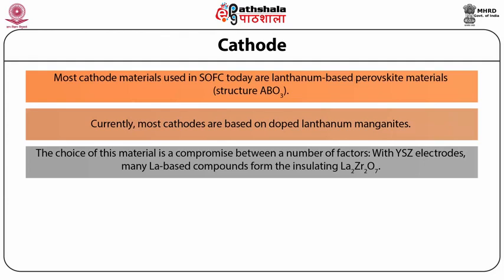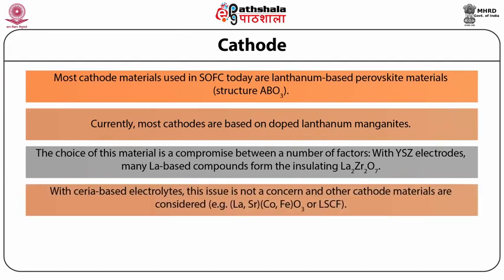With YSZ electrolyte, many lanthanum-based components form the insulating lanthanum zirconate. With ceria-based electrolyte, this issue is not a concern and other cathode materials are considered. For low temperature cells, the conductivity of LSM, that is lanthanum manganite, is inadequate and other materials such as strontium doped lanthanum ferrite, that is LSF, are considered.